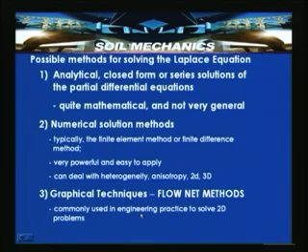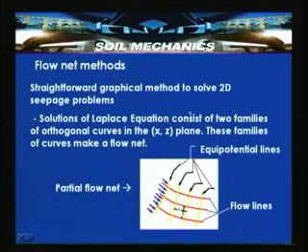of geotechnical structures. So, these flow net methods are basically straightforward graphical methods to solve two dimensional seepage problems. Solutions of the Laplace equation consist of a flow net, which means two families of orthogonal curves in the x and z directions, and these families of curves are called a flow net.